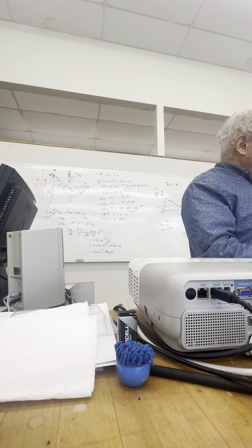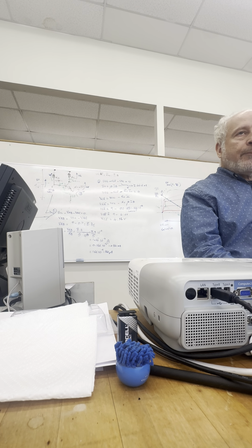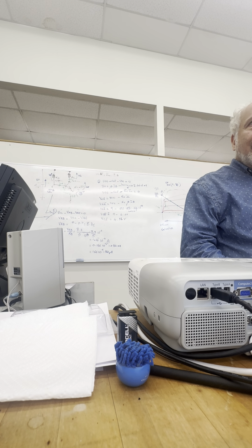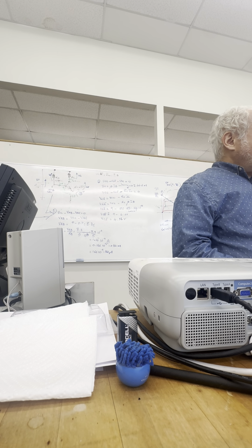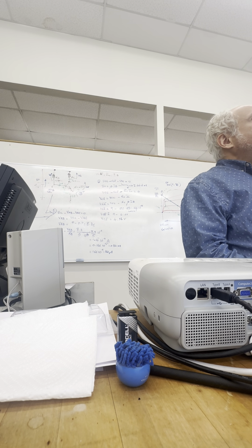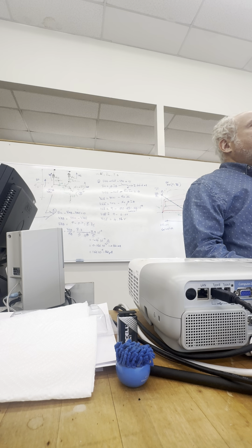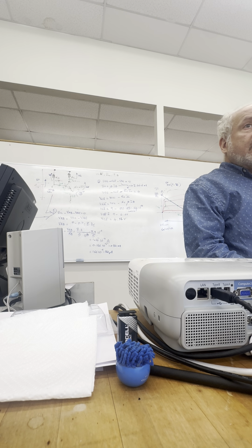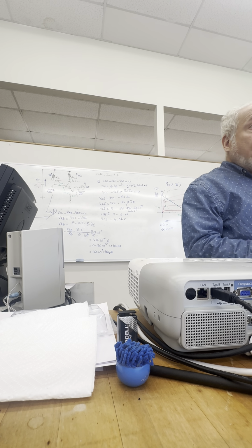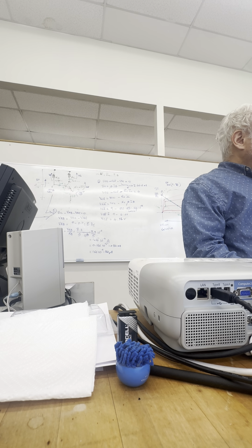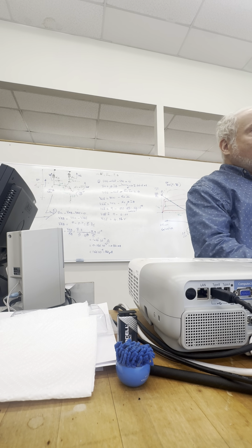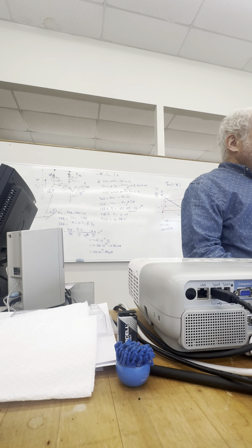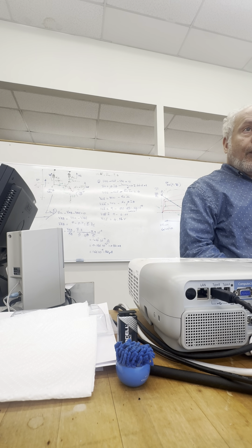This is where engineering comes in. You start looking through specs and say, how do I come up with values? How do I come up with these RCs? Well, it all depends on the environment you're operating this thing in. You're going to start asking questions like, okay, my ambient temperature is 25 Celsius. I'm looking at the spec sheet. It says do not exceed 1 amp. Beyond that, there are no guarantees how that motor will behave. Does that make sense? It will overheat. All right, well, I'm going to be at 0.8. If they say the happy medium at that temperature is 0.8, 0.7 within that range, yeah, good, I'm going to be there. So what would it take for me to get that? Well, I'm going to saturate the transistor to drive the motor all the way. Do you agree?